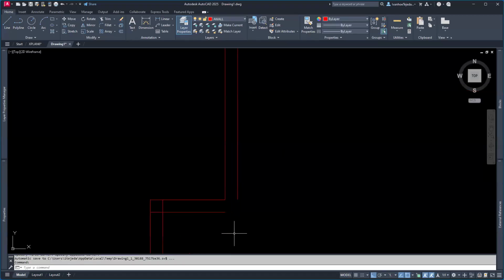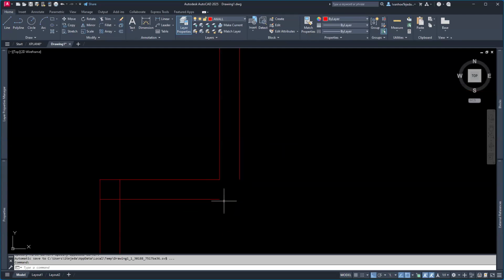I'll see if I can do the same thing here, but I might run into a problem. So I'm going to try F, enter, C, enter. Is it going to work? No. 1 second. F, enter, C, enter, like this. No, see, it did something strange. So that won't work there. So in this case, I will have to type just F, enter, and fillet at these corners. And then over here, F, enter, C, enter, crossing, done.